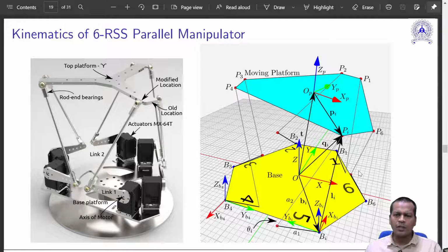So let us work on one of them, that is the Zamanov configuration, kinematics of a 6 RSS parallel robot. Now it is just an extension of what we did before, I won't go too much into the mathematics of this. It is not very complex, but in order to finish in time, I will just give you the philosophy of that. You already know this distance, Li, through the 6 UPS Stewart platform: you just calculated this length for any configuration of the top platform. So if you know Li, that is the length, it was basically in this frame.